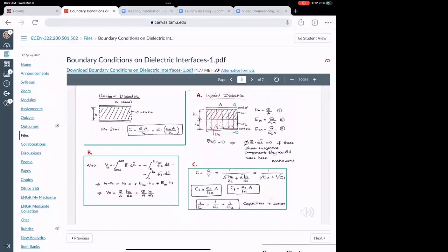Okay. What happens now if your two metals are on different, so you have a difference in dielectrics between the two. One, for example, let's assume that one is silicon. The one that I have graded with these lines is like silicon oxide. They have different dielectric constants. Silicon oxide is close to 4, somewhere between 2 and 4, depends on how you do it, and silicon is 11. What happens in the capacitance between these two conductors?